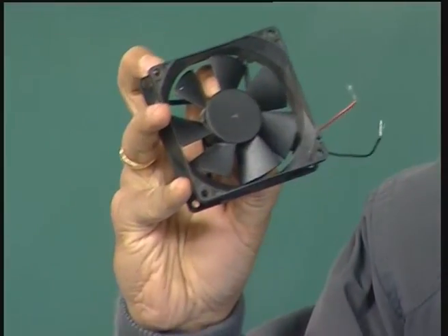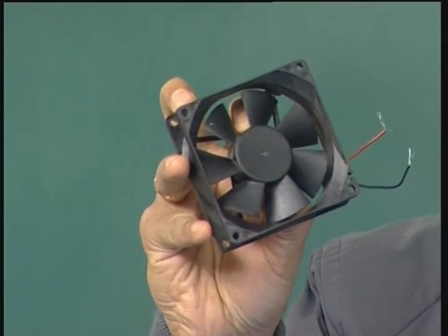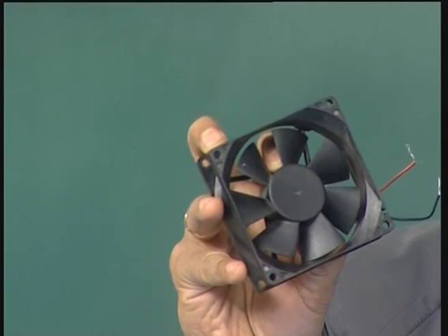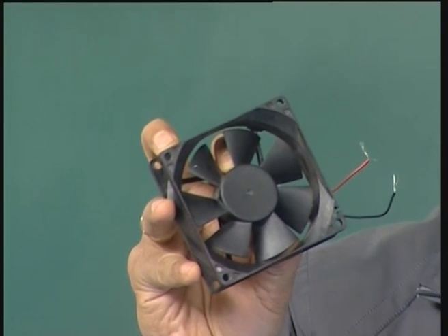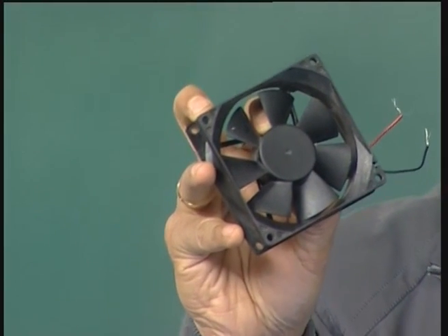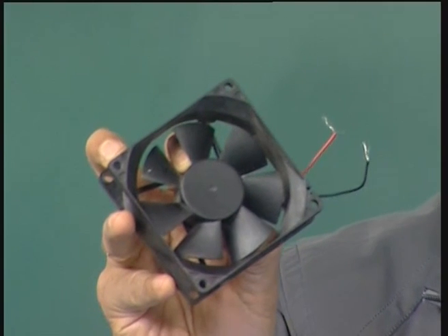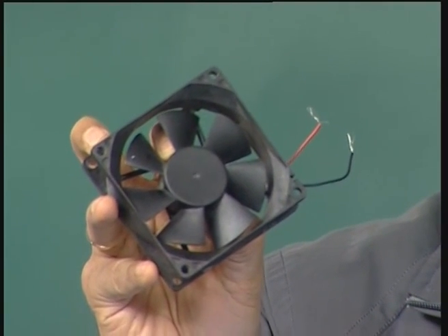okay, and this is a brushless DC motor, because this fan is going to run for years together without getting damaged. So, if we go for a simple DC motor having brushes and commutators, we have frictional contact there, the contact will develop problems, and once the fan stops, the cooling will also stop. So, this fan is supposed to run in dusty environment without any problem, because it does not have any brush.